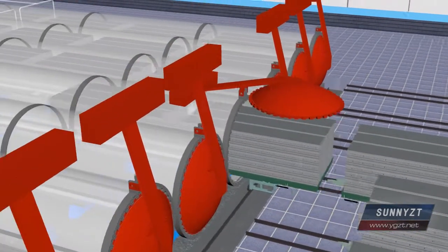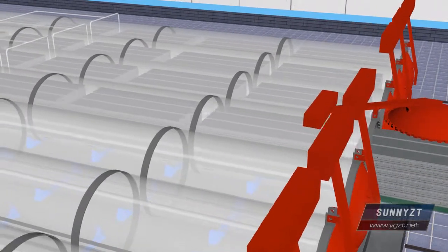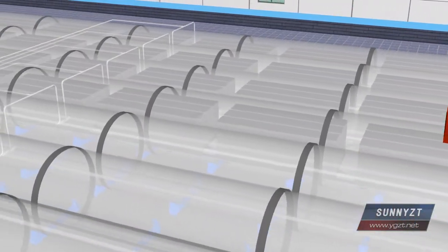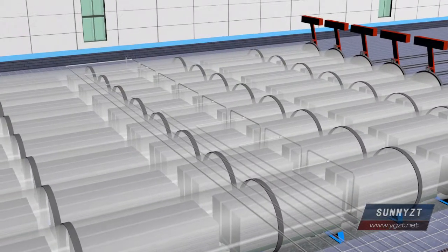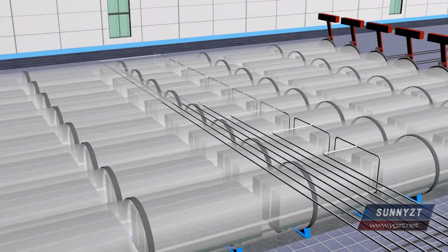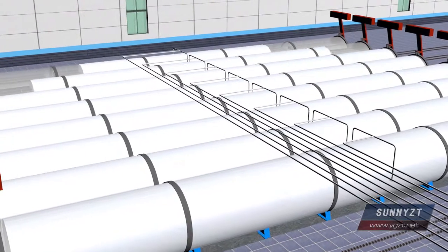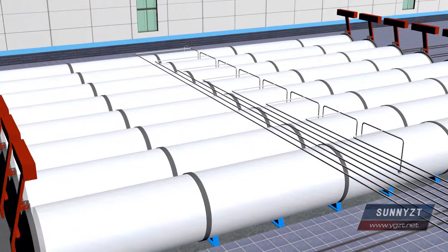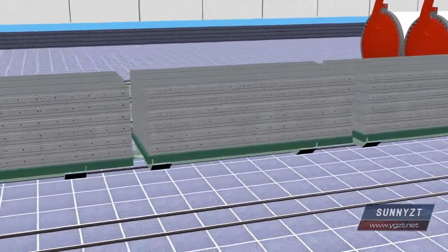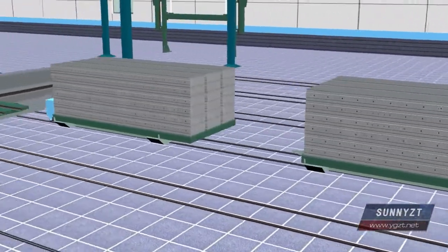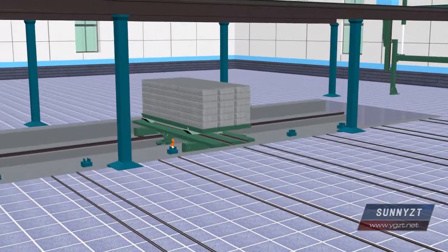Use the dragger before the kettle to convey the marshaled steam curing trolley and the green body into the steam curing kettle. After 8 to 10 hour high temperature and high pressure curing, the green body, which has been autoclaved and steam cured, is dragged out of the kettle from behind the kettle and moved under the mobile severing machine.